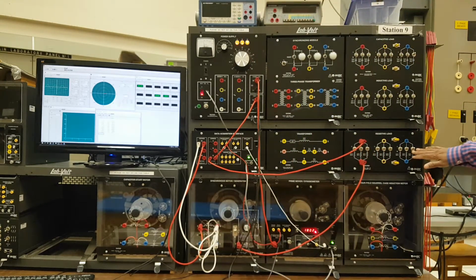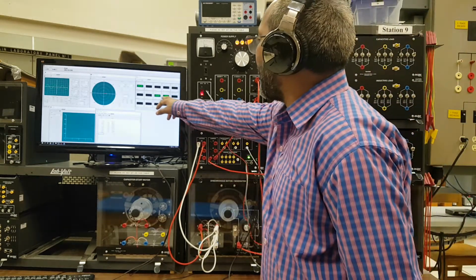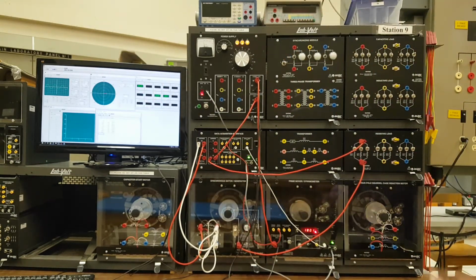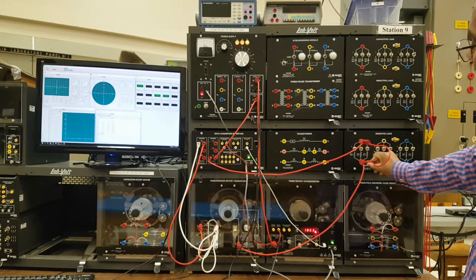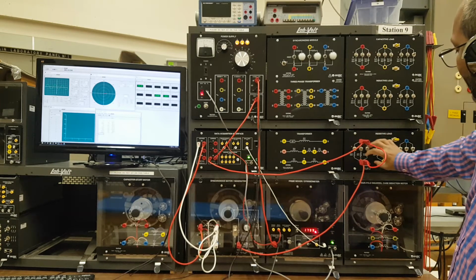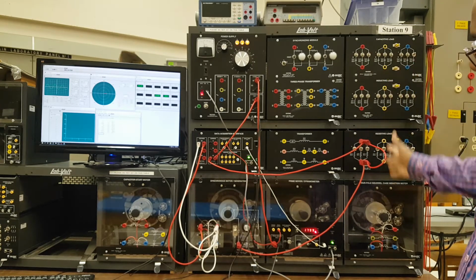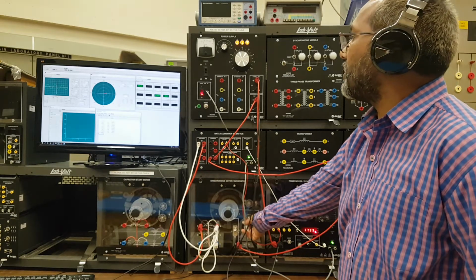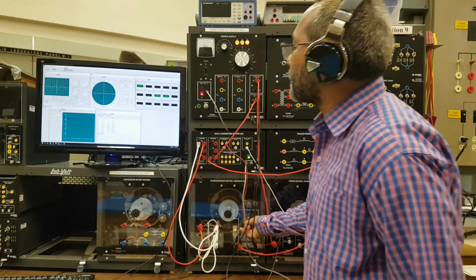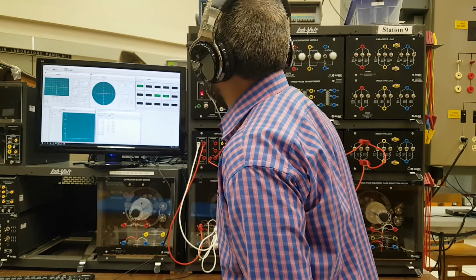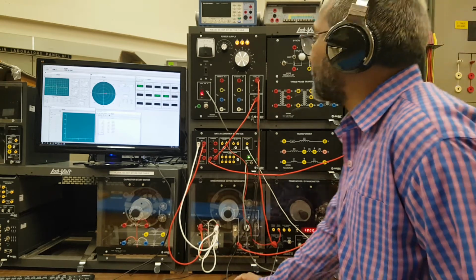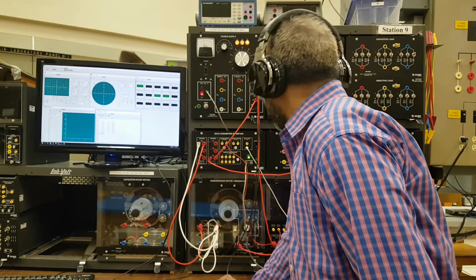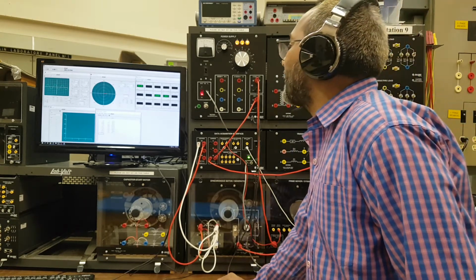Since all the resistors are now done and the current is 0.36, I want it to increase more. So what I will do, I will just short it as per the instructions. Just short these top and bottom terminals. Now this control is over, done, bypass. Now we have only this one control, so we can change it in steps of 100 milliamps. 0.36 was there before, and 0.42 is the next one. So I will just take the reading. And speed is not changing much, so I will take the reading now.